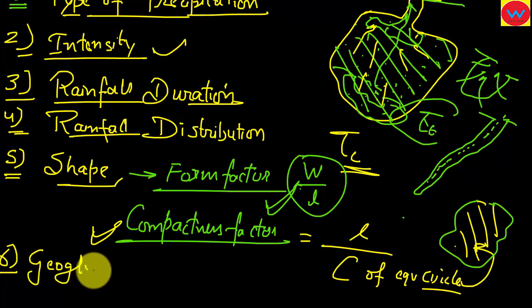We can easily understand that coarse texture sandy soils will tend to give rise to little runoff. That is, there will be more percolation or infiltration in coarse grain because it has high permeability. Voids are bigger. On the other hand, fine grained soils, compact clay soil will tend to yield more surface runoff because clay has low permeability.